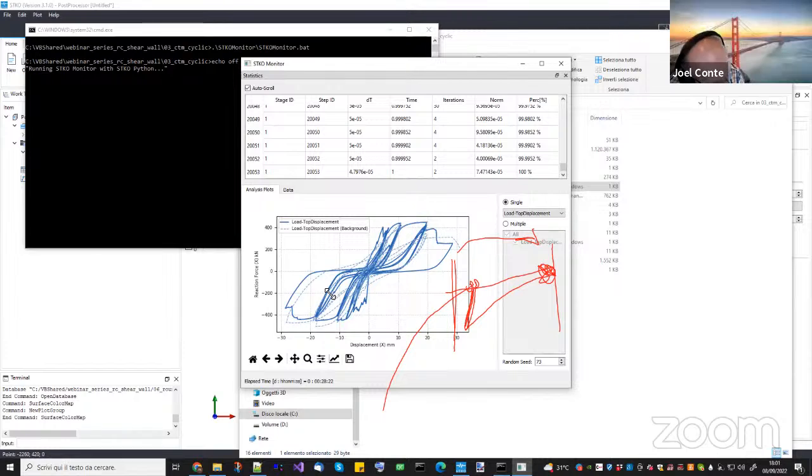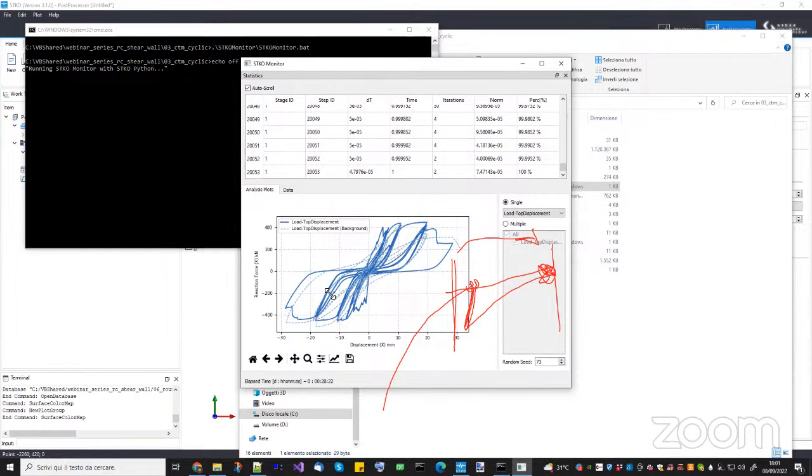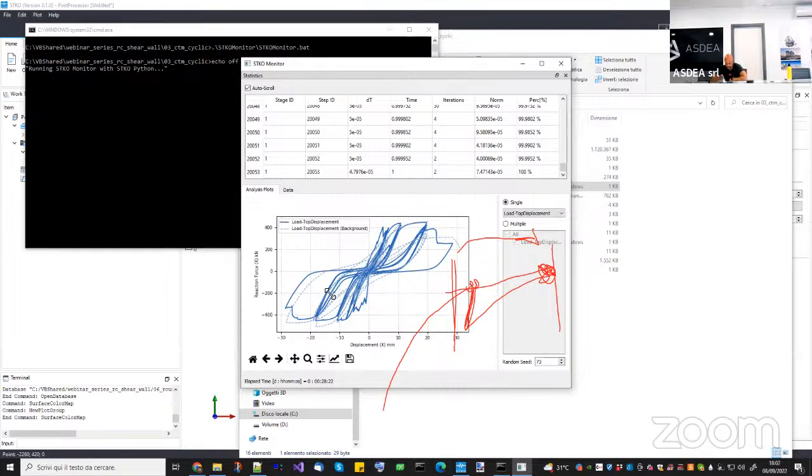In my opinion, previously you were affected by bifurcation, so that's why I wanted to increase the time steps to see whether my problem has this kind of issue. If it is monotonic, you can try to use the arc length method. Sometimes it works for passing this. The problem with the arc length method is that it will be a mess if you want to do the cyclic pushover.